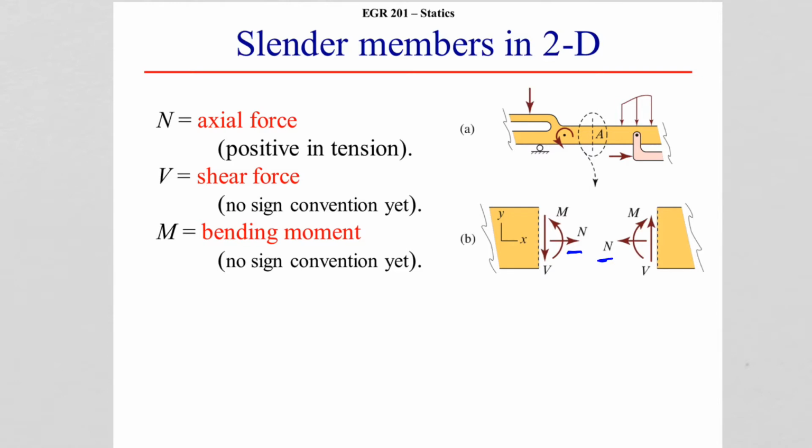The sign convention that we will use, we will always draw these pulling away from the member itself. We also have something called shear force. Shear force acts along the surface of our cut. And you'll see between these 2 halves, of course, they have to again be equal and opposite. The convention, it says no sign convention here, but this is the convention that we will be using when we have a beam. When we have other structures that aren't beams, it's more open-ended that way.